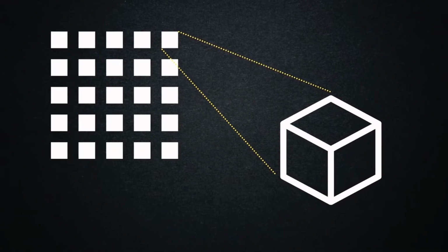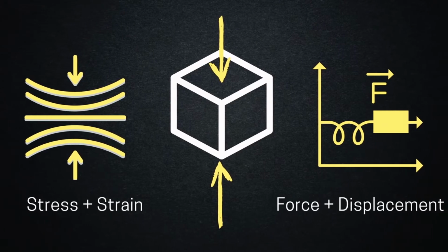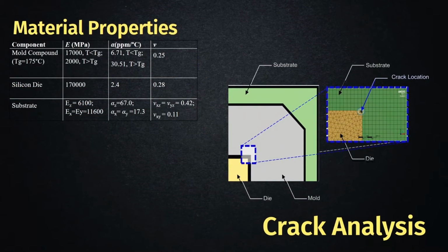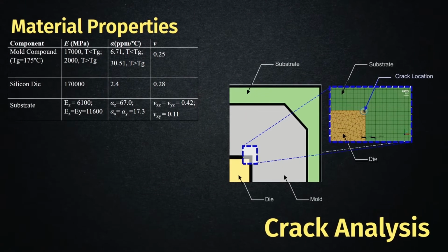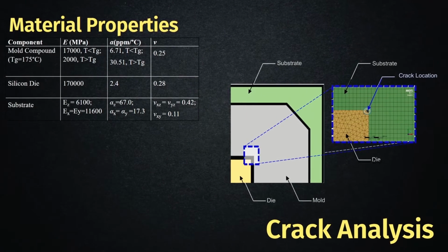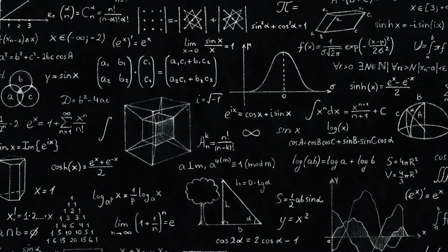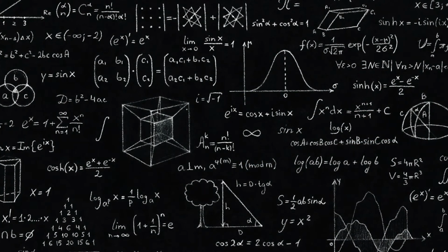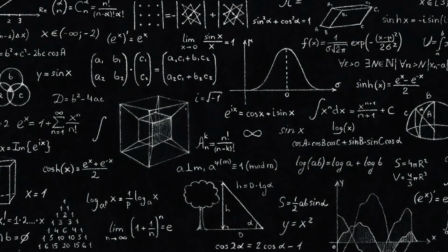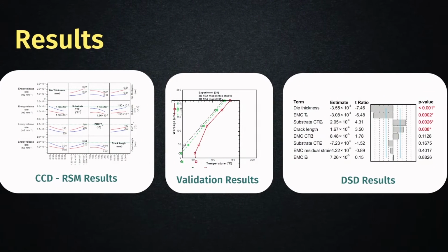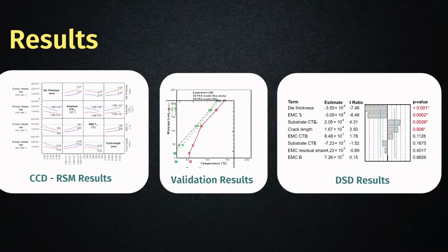Next, let's create a description for each piece. Oftentimes, it is a linear description of stress and strain or force and displacement. Then take all the pieces and show how they relate to the other pieces using compatibility and continuity equations, which will result in a large system of equations. Assemble those equations together to form a matrix. Then we solve for the unknowns with matrix manipulation.